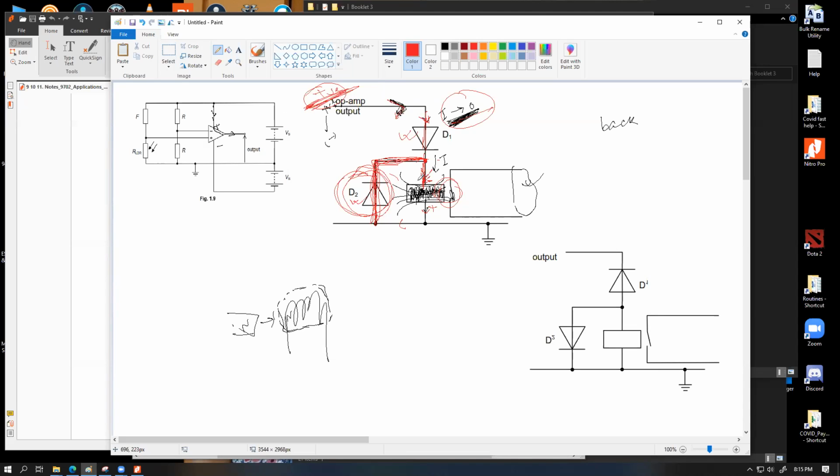So how would the damage occur, sir? I didn't really understand. The damage occurs because these components that we have over here are usually not designed for a really large amount of current, for example, 1 or 2 ampere or this kind of current values. They are designed to operate at a certain voltage value, but for a very small amount of current. They are basically used for some signal decision making. So you cannot have a pretty large amount of current that works through here. If we do provide a very high amount of current, there is a possibility that the electronic components inside the op-amp circuit, which we did not discuss, but there is a series of transistors and diodes merged together, which basically does the job inside the op-amp, can become burned from the I square R effect of that back EMF current, which is significantly larger than the regular current value of the solenoid for that small duration of time. So to divert this excess current, we're using a smaller loop. Exactly.